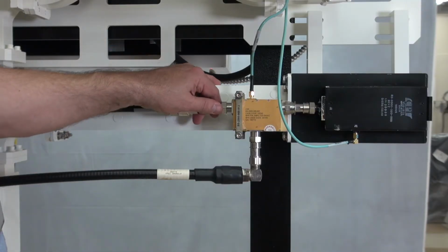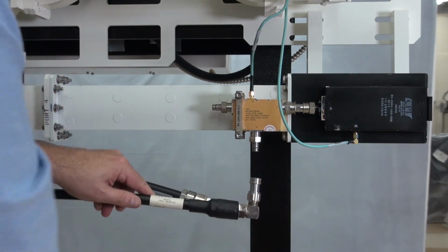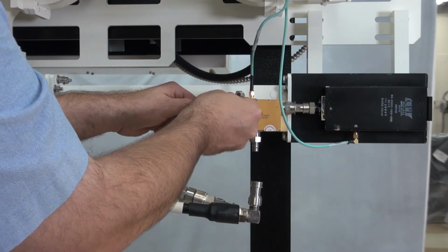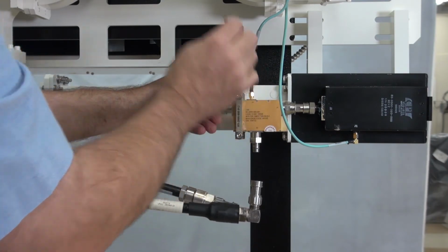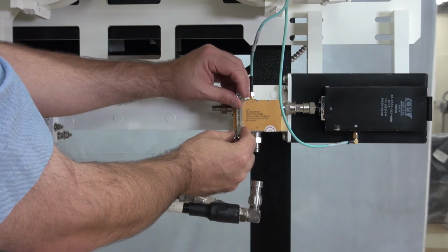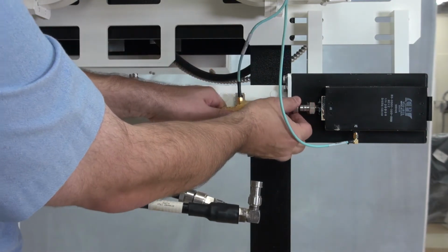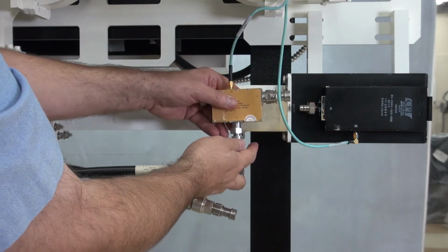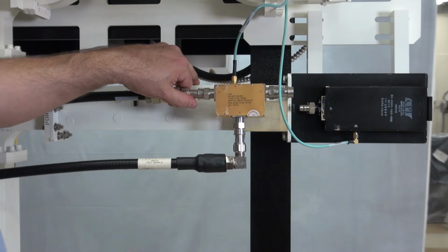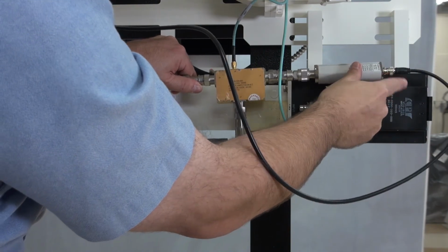Disconnect vertical LNA from vertical TR limiter as follows. Disconnect cable 2W555 and 2W576 from the LNA. Remove the LNA clamp. Disconnect the LNA from the TR limiter. Reconnect cables 2W555 and 2W576 to the LNA. Connect the noise source assembly to the input of the vertical LNA.